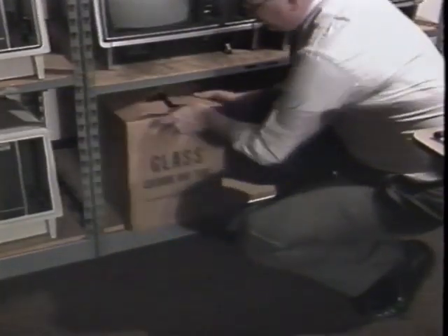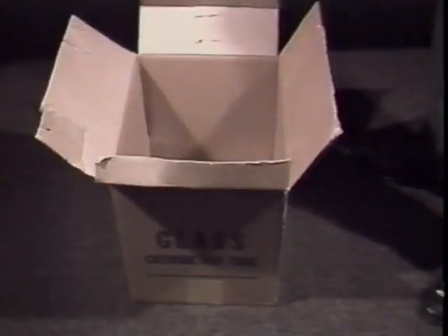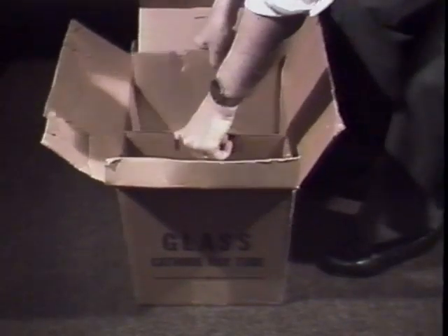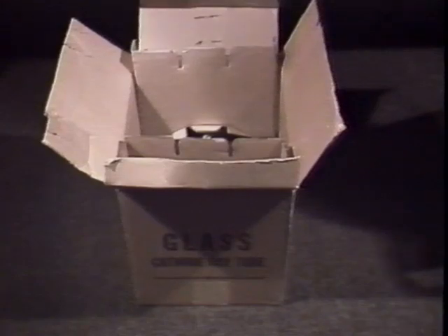Always store and transport CRTs in their original packing. Take care not to drop CRTs. Do not store them on high shelves or transport them without securing them. Whenever you dispose of a tube, first disarm it by cutting the nipple. If possible, place the tube in its packing carton beforehand. If packing is not available, use a sturdy, deep wastebasket. Do not assume that a CRT with a cut nipple is immediately safe. Allow at least a minute for the pressure to equalize.